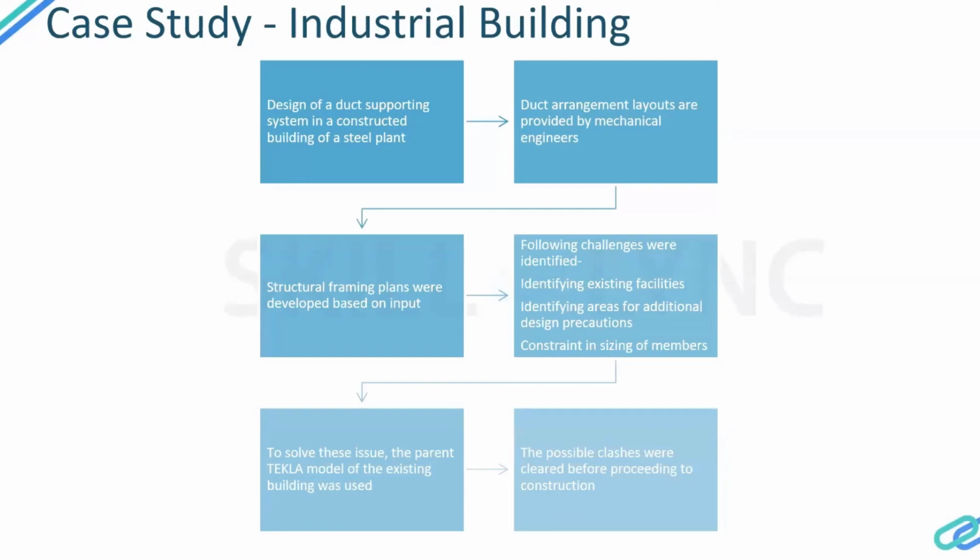We could actually see all this happening even before we were in the design phase. So when all these clashes were cleared before construction, we could easily go into the construction phase without any delay. And also, it eliminated the repetitive design process. Like, when I know where my space is to do a support system, I will design accordingly. It's not like I have to do it again and again. It's not like I position it somewhere and later we realize, okay, there's a bracing here.